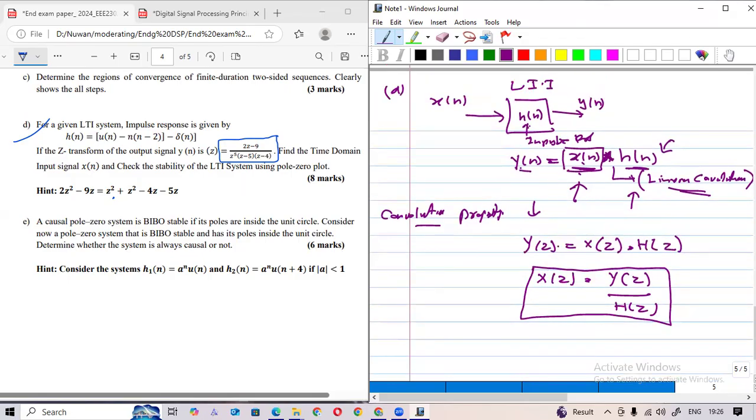So in this question, you are given Y(z) and you are asked to find H(z), okay? Sometimes you will be given x[n] and h[n], and still you can convert. You can convert x[n] into X(z), h[n] into H(z), then you can get the multiplication, then you can calculate Y(z), and if you take the inverse Z transform, that is Z^-1 of Y(z), you can get the signal y[n].